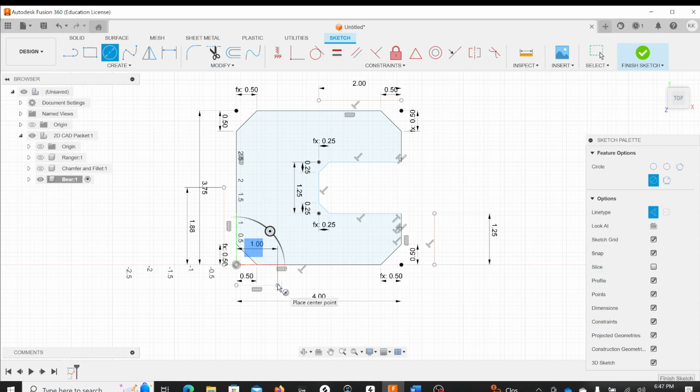I am going to come down here, hover, and then come up, and then watch how it snaps in as I meet that other point. Boom, right there. Click to start your circle, and see how it's drawing that dotted line right now? Because I was in construction mode. I'm going to come over here. I'm not clicking anything. And sure, the circle got huge.